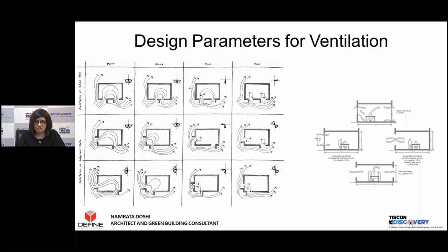Now, what the individual must have tried to do is give two openings on one wall, like the strategy I talked about before this. But if you see, he's failed at achieving ventilation because he's given notches on either side, and the air, instead of circulating with a certain pressure, is getting blocked. He's not achieving the velocity he wants, and so the ventilation is poor.